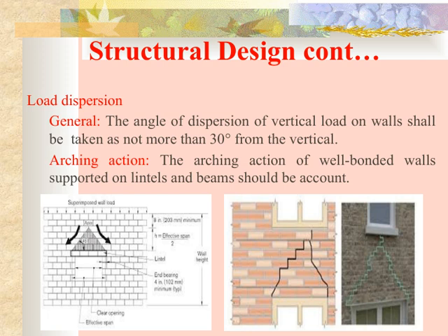Additionally, we need to account for the arching action, especially in well-bonded walls that are supported on lintels and beams. This arching effect can significantly influence how loads are distributed across the structure, providing additional stability and strength. Recognizing this behavior allows us to design more resilient walls that effectively manage the load transfer, ultimately supporting the overall integrity of the building. So, in summary, understanding and properly designing for load dispersion and arching action are key to creating safe, durable structures that perform well under various loads.